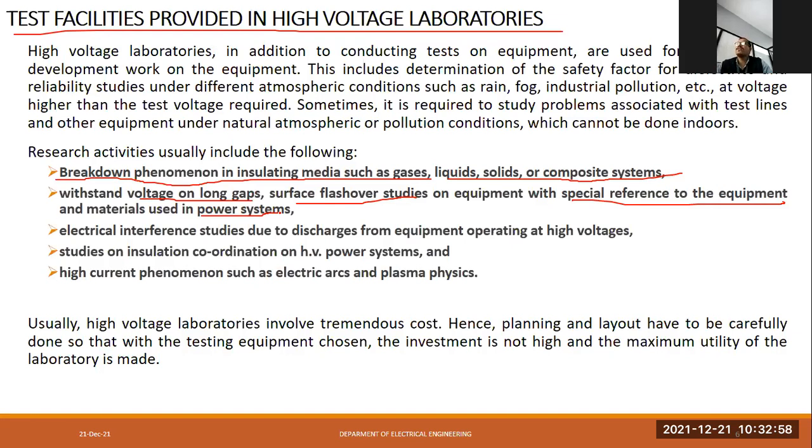And whatever the withstand voltage, suppose there is a gap, and we are increasing that gap, at that moment we will check whether it is withstanding or not. Then what does surface flashover mean? Due to the corona, there may be radio interference, and due to that there may be flashovers, meaning wet flashover and dry flashover. Those studies we need to consider for the specific equipment and the specific materials used in a power system.